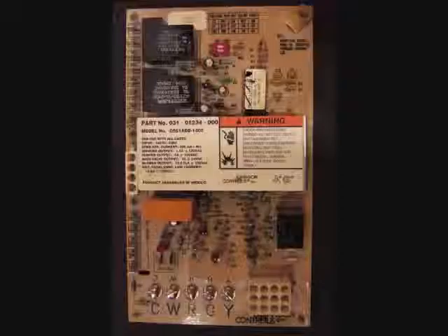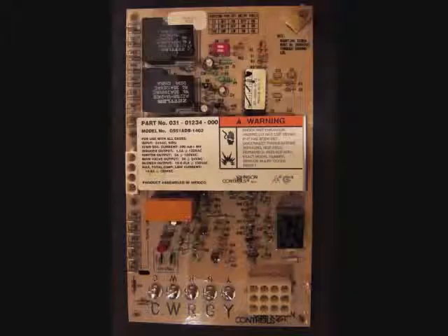Hall effect. This is an end cap to the motor and has 3 wires, red, white, and black. This senses shaft rotation and sends a signal to a circuit board. This type is usually diagnosed by a series of flashes on the circuit board. These can be deciphered by a legend, usually on the inside panel of the unit.